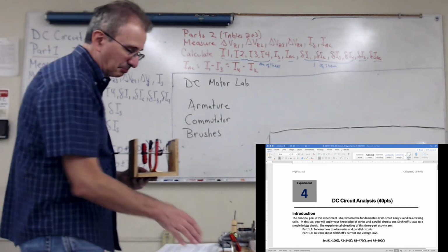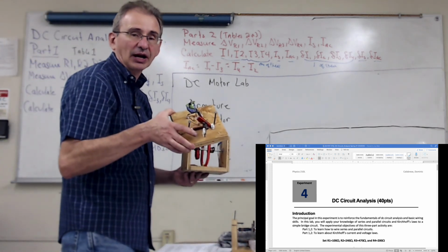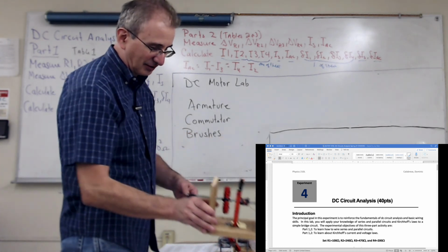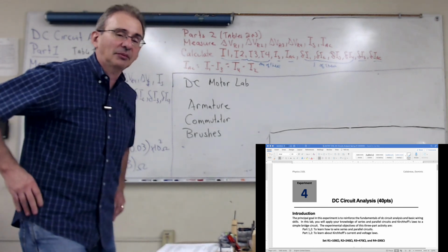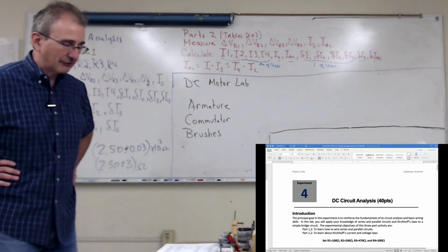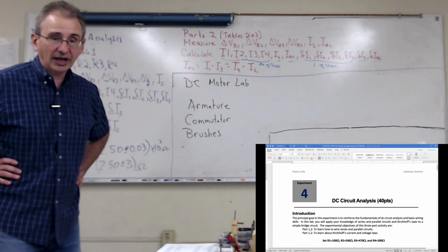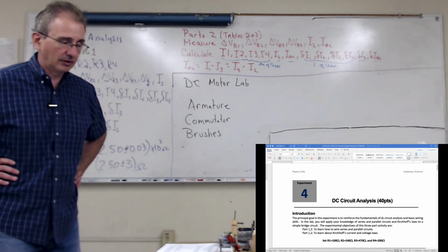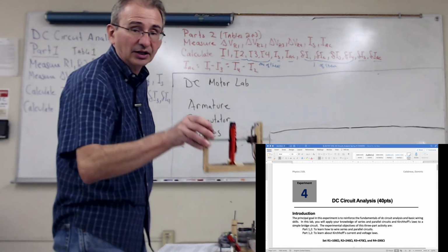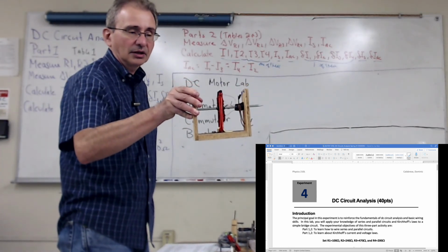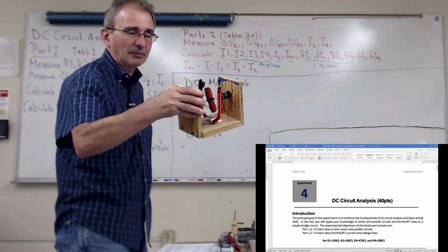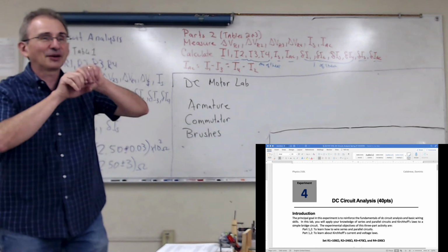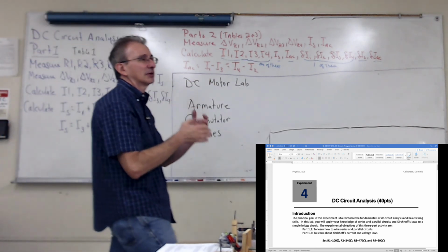So you don't have to build exactly what's prescribed, but if you look at the document, it tells you what the rules are. You have to hook up everything in series, not parallel, and your armature has to be a certain diameter. The minimum diameter is given. The problem with this one too is that the armature was too heavy. And the moment of inertia, because of the wire wrapping around the armature, the mass wasn't distributed uniformly. That makes your moment of inertia higher.